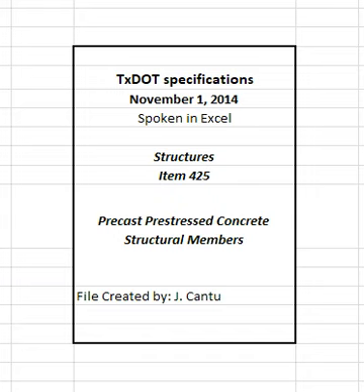3.1 Handling, storing, hauling, and erection of precast prestressed concrete members. Properly handle, store, haul, and erect all members so that they are placed in the structure in a manner to avoid excessive bending stresses and without damage. Lift members with approved lifting devices as shown on the shop drawings or as approved. Maintain beams in an upright position at all times, and raise and support them near the ends to prevent torsion unless approved on shop or erection drawings.